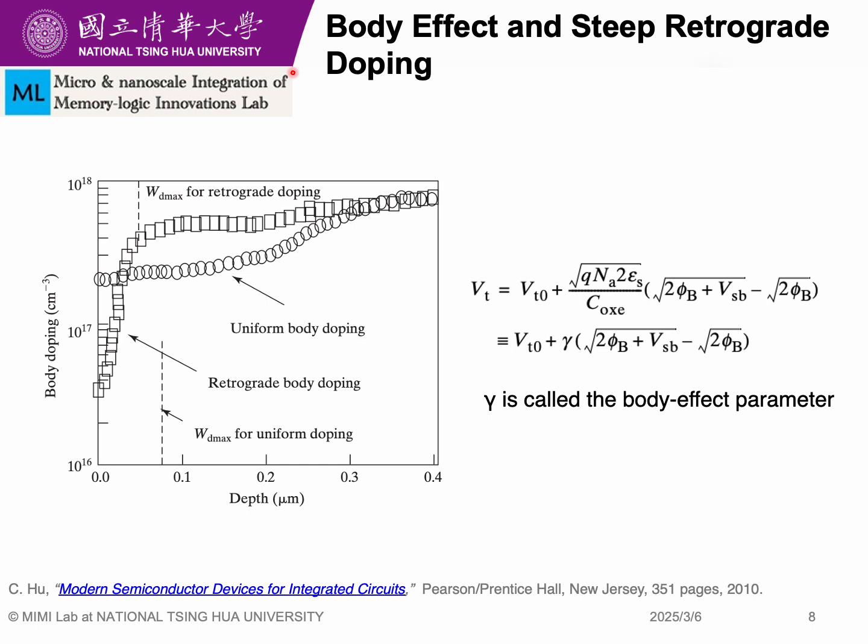As a result, modern transistors exhibit a more or less linear relationship between Vt and the source to bulk voltage. A linear relationship means that the maximum depletion region width and the ratio of the capacitance in the oxide and the depletion capacitance are independent of the body bias.